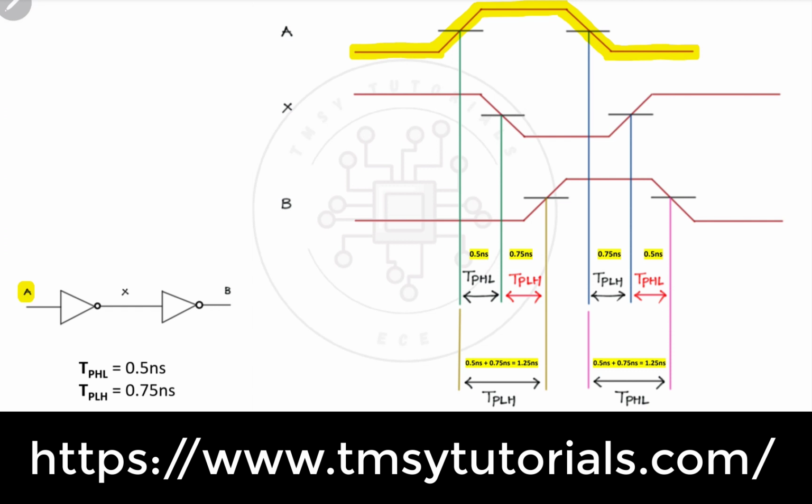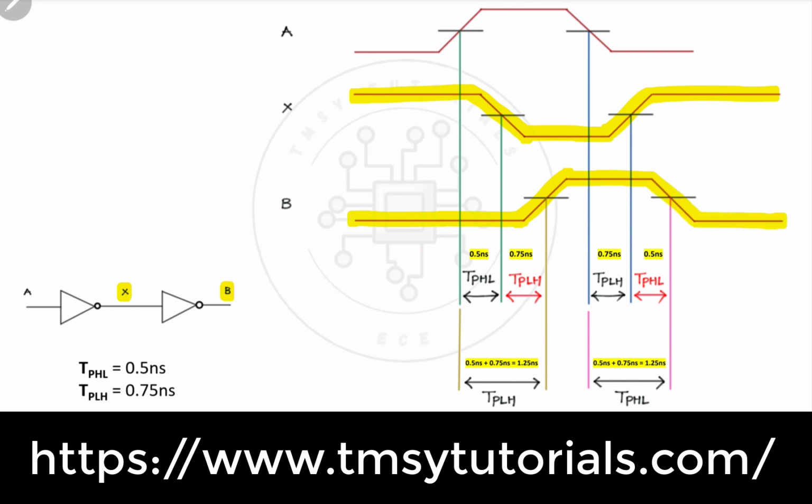This is what I am applying at A, and X is nothing but the invert of A. So simply it will get inverted, that is, from high it will go to low, again from low it will go to high. Now this X will act as input for the second NOT gate and you will get the output as B. So X is coming from high and going to low, again from low going to high. Now B is simply the invert of X, so it will move from low to high and again high to low.